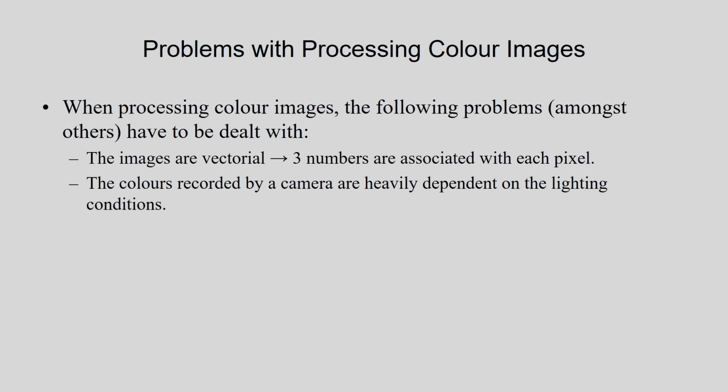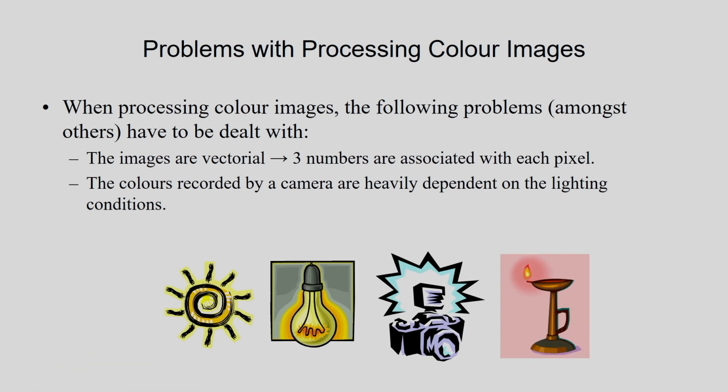Now, I have highlighted the problems with processing of the color image. One problem I have already explained, that is the problem with marginal processing. Marginal processing means the RGB components are processed separately, and then color distortions take place. One example I have given is the scalar median filter, and for this I have discussed the concept of the vector median.